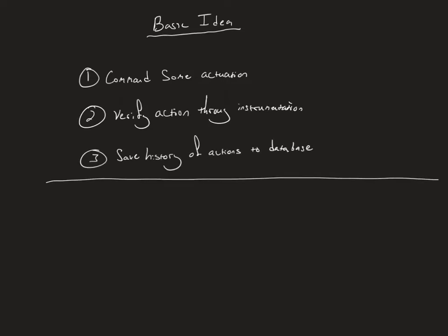One of the ideas that industrial control systems borrows from the study of control theory is the idea of a feedback loop. So it's important here to notice how that loop comes into play. At the heart of the loop, we have the PLC. So the PLC generates an output, and this output takes the form of an actuation. So the PLC internally in software turns on an output which causes in the real world an actuator to actuate.